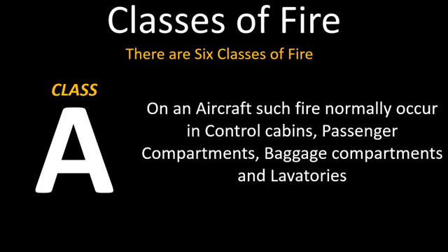On the other hand, such fires can also occur in baggage compartments and laboratories, where crew access is limited or even impossible during flight. In these areas, monitoring is primarily accomplished with electrically powered smoke or flame detector systems.